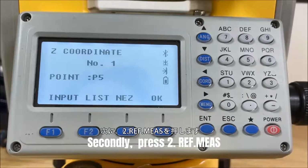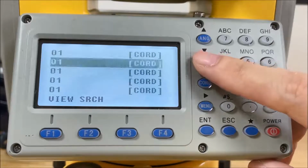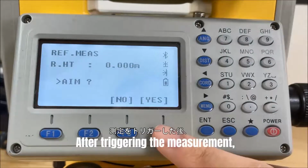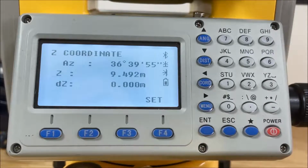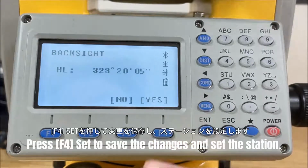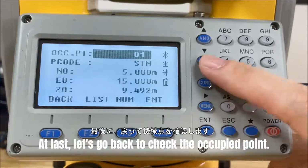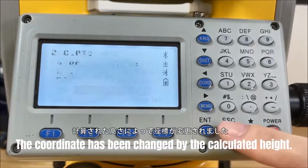Secondly, press Refer Measurement. Select a known point. After triggering the measurement, the calculated height is displayed. Press Set to save the changes and set the station. At last, let's go back to check the occupied point. The coordinate has been changed by the calculated height.